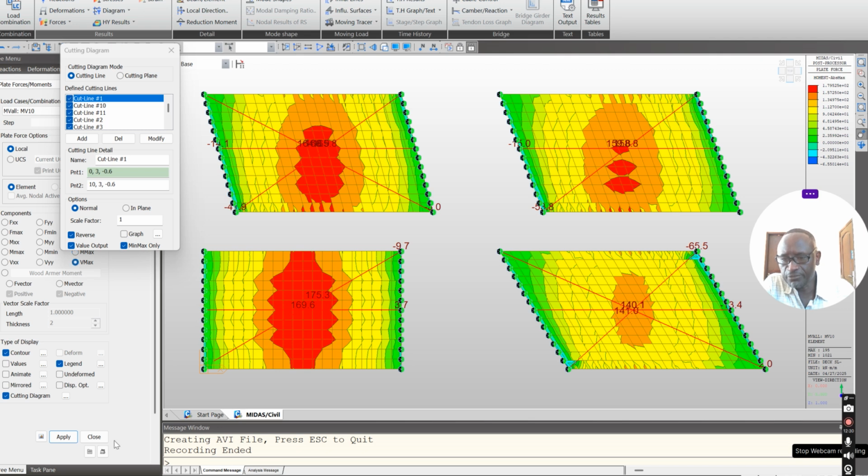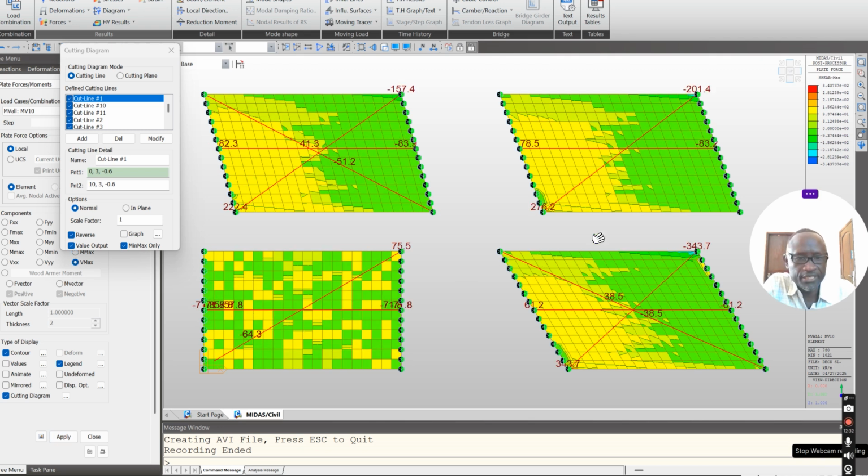What about the shear force behavior? This is how the shear force pattern looks, and you can see the pattern changes. You have 75 at the normal deck diagonal, so it's basically 75 all around in a way. Then you have 222 and then 157. So we have 82. This is for a 15 degrees skew angle. You can see there's a jump of almost 3 times, from 75 to 225 or 223 there.